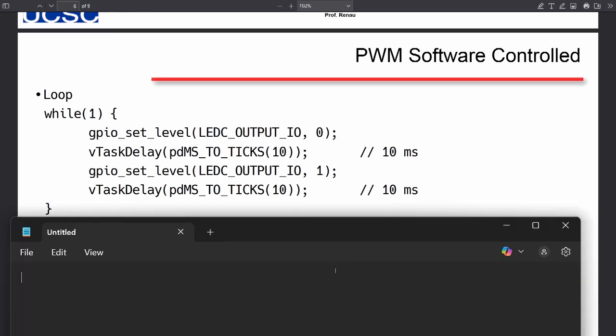Okay, so we probably need both sleep functions to take the same amount of time as these two. So what would the total amount of time be? The total amount would still need to be 20. So that would mean if we want it to be split up into, I guess, 80% and 20%, what's 80% of 20? 16. Yeah. And then finally 4. So it would be off for 16 and then on for 4 for a 20% duty cycle.